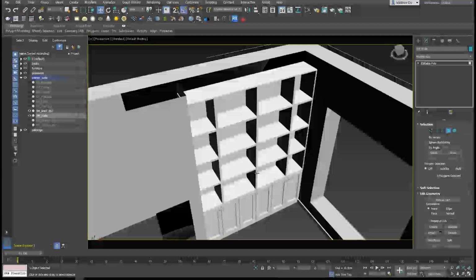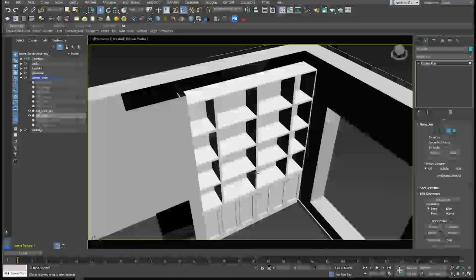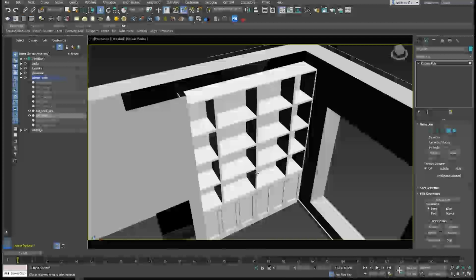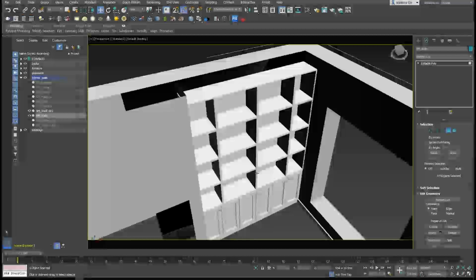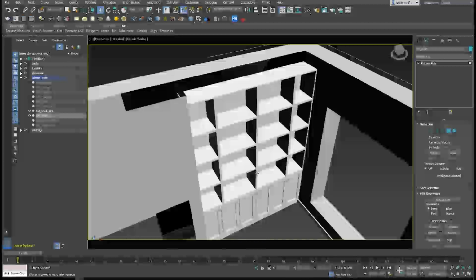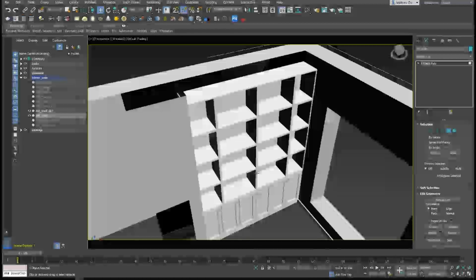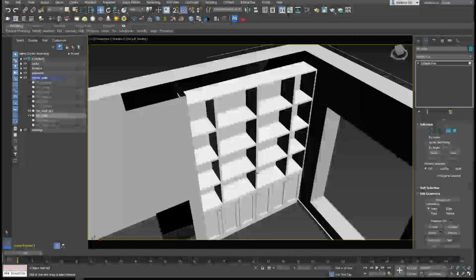Now, another option would be to use LODs. And again, this is mostly for scenes that are very large and exterior scenes. If you've been following along and you watched the LOD video, you'll know how to create LODs for Unreal. And then generally what you'd want to do is, for any objects that are causing Z-fighting issues at a greater distance, have a lower LOD for that object that removes whatever parts are offending, whichever parts are causing the Z-fighting.